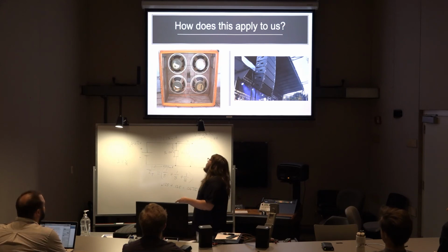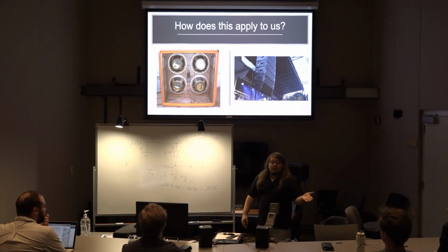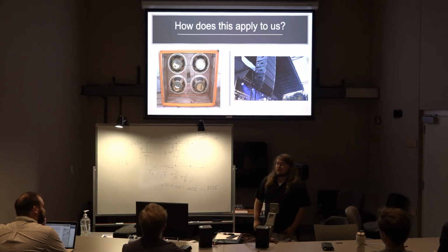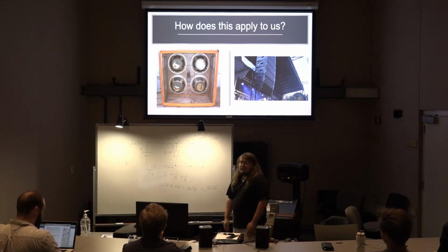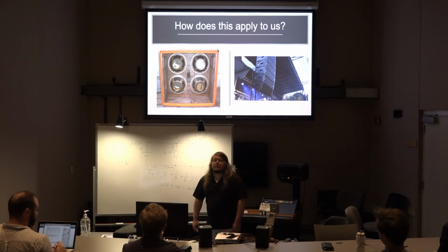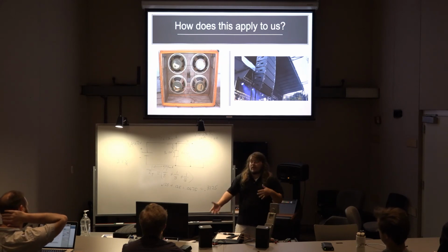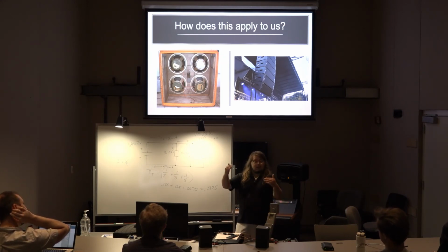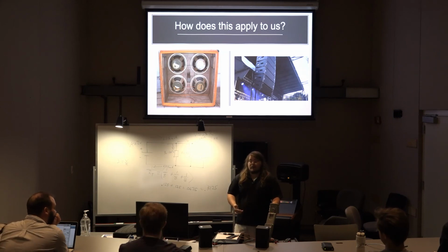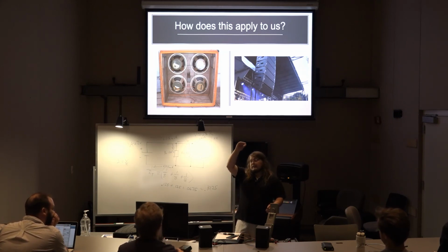The second part of that, on the right, as I said earlier, you guys are flying a PA at your Nolansville show. It's going to look a lot like that, the line array. It's the classic, the staple of all live sound reinforcement these days. Well, how do you get all of those speakers their power? It's a combination of series and parallel circuits. You may hook them all up in parallel, depending on your power amp, or you may say, well, I need this guy in series with these 2, and then that whole combination's in series with this, or in parallel with this, to provide the right load on the power amp.